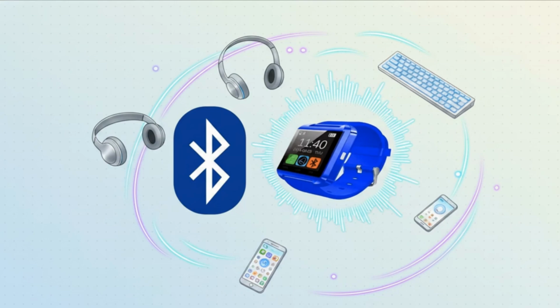Enter Bluetooth. Bluetooth uses very little power, making it absolutely perfect for short-range connections, like linking up your smartwatch or wireless headphones or your keyboard. What's super cool here is how it actually maintains a reliable connection in a room totally packed with other signals. It uses a smart method called frequency hopping spread spectrum, or FHSS. By constantly hopping around different frequencies, it actively dodges signal problems and interference. It's just a highly efficient way to link devices that are close to each other.